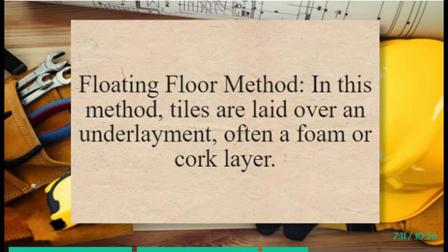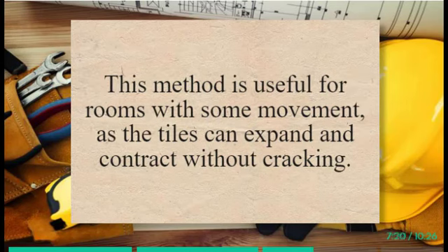Floating floor method. In this method, tiles are laid over an underlayment, often a foam or cork layer. The tiles aren't directly adhered to the subfloor. This method is useful for rooms with some movement, as the tiles can expand and contract without cracking.